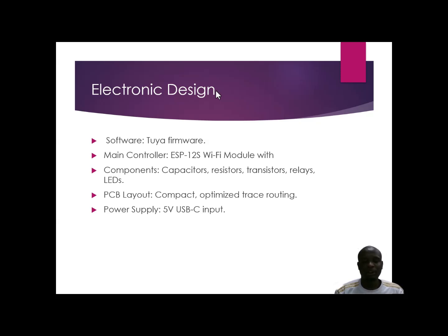Our components are a Wi-Fi module, specifically the ESP12S. This is our main controller that enables wireless communication, letting us control the switch via smartphone or smart home systems. We have relays that act as electronic switches to turn on and off the lights or loads.